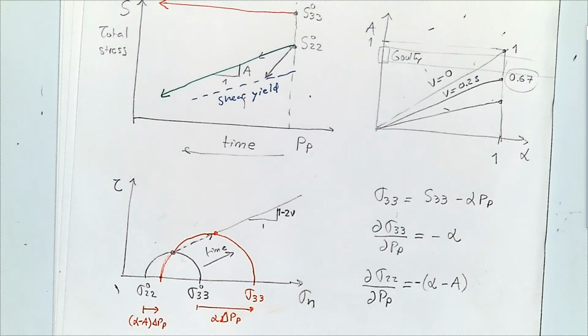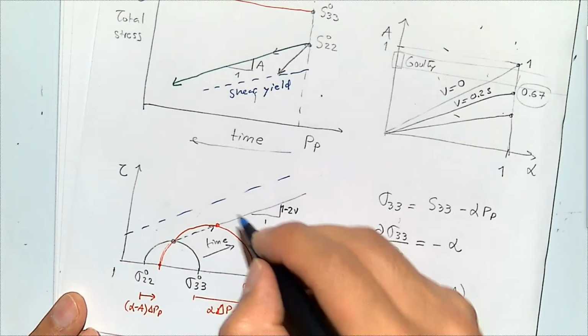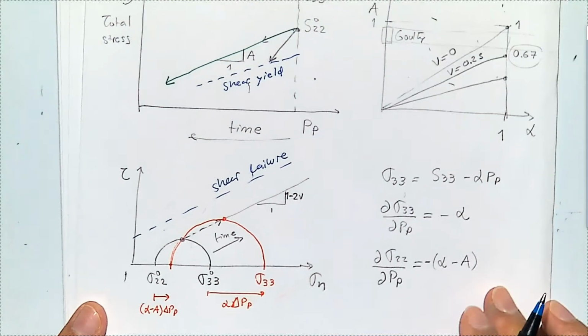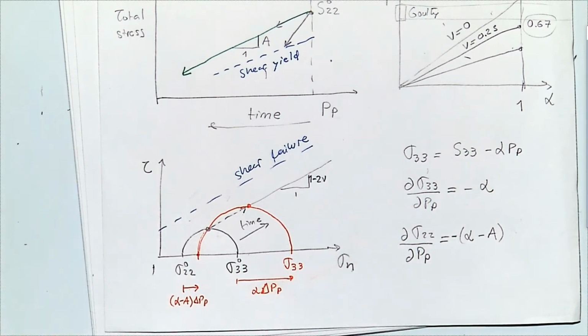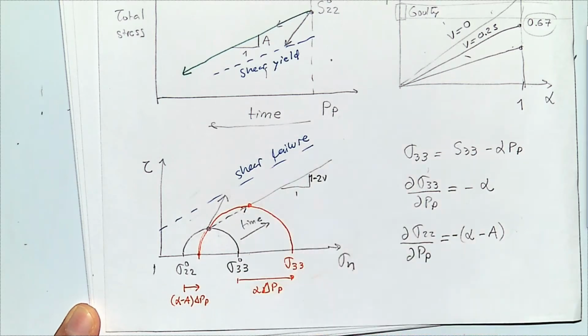And if this slope is too big, this is why we said that before, we could get sometimes to shear failure. So we know now very well that shear is going to be a function of the effective normal stress. And again, if this is too steep, it could hit the shear failure and could cause fractures inside the reservoir.